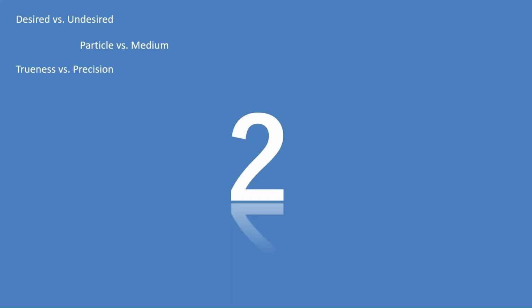Precision is easier than trueness because what we consider as true is really difficult to answer. And also whenever we are looking at some numbers provided by the company, keep in mind that you have to ask the question, what is the technique used to generate the number? So what is the equivalent sphere? And look at them together. The two things need to be together. You cannot look at the number by itself without looking at what is the equivalent sphere, what is the technique, what's the underlying principle of the measurement.